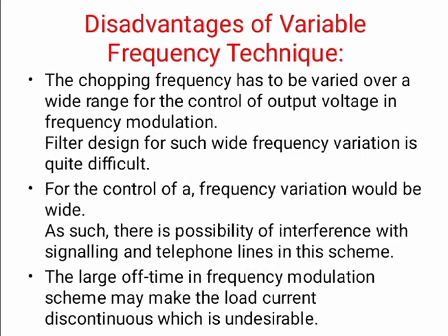In variable frequency systems, a large T-off time in the frequency modulation scheme may make the load current discontinuous. So if we take a large T-off time, the load current becomes discontinuous. Discontinuous means it becomes zero. So it is undesirable.